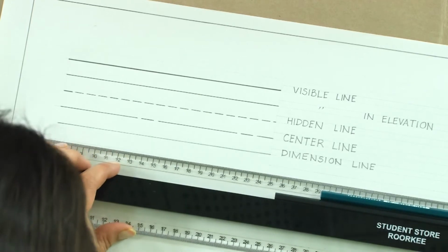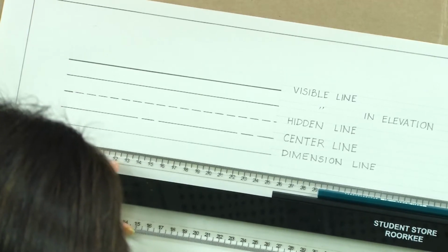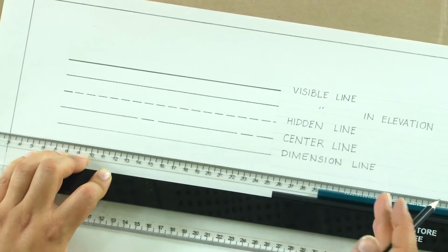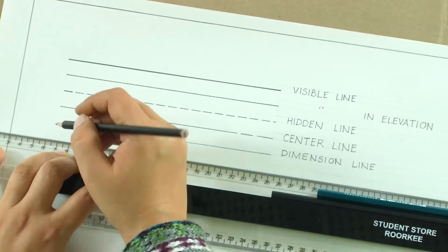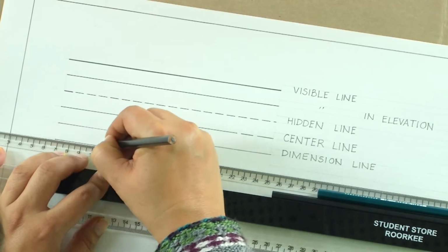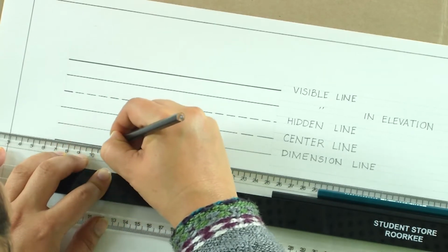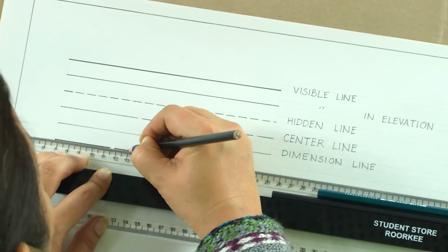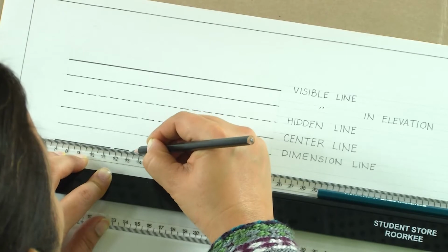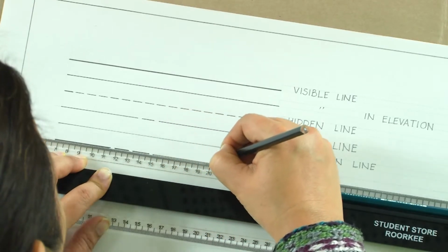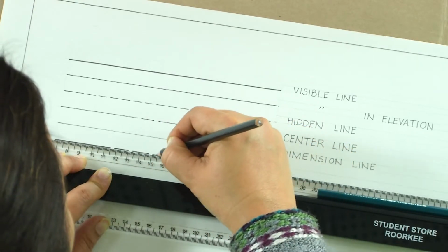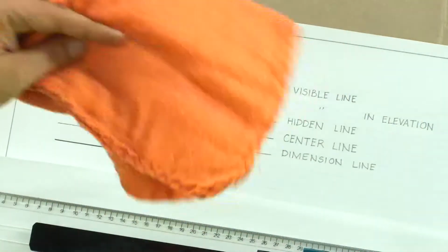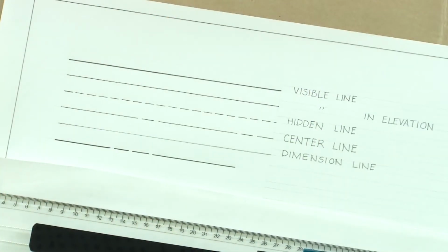Next, we have a section plane line. A section plane line is a very thick line, which is also called a cutting plane. So, what we have in this one is a very thick line, a bigger dash, then two smaller dashes. It is very similar to the center line, but this is what we use for the cutting plane line.